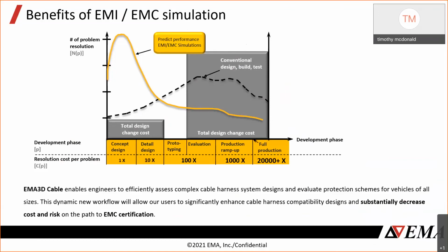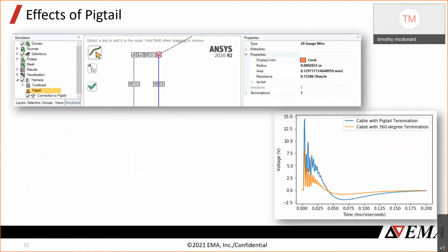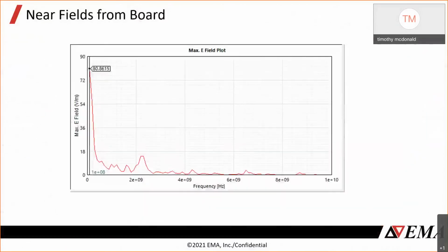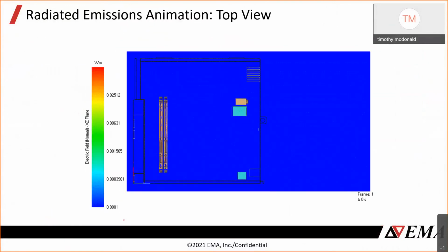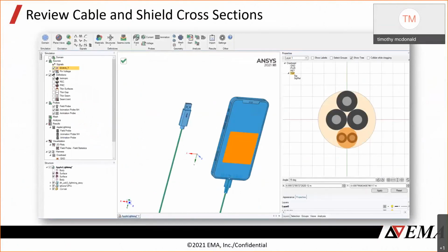All right, and another question from Sophian. Generally, most of the models fail at the resonance frequencies. Could you show a comparison between the measurements and the simulation at the resonance frequency? Yeah, that's a limitation. The resonance makes it hard to measure transfer impedance at the resonant point. But in some cases, we've shown some of these S-parameter characterizations where we can capture these higher order effects that are frankly kind of hard to characterize without a very good fixture.